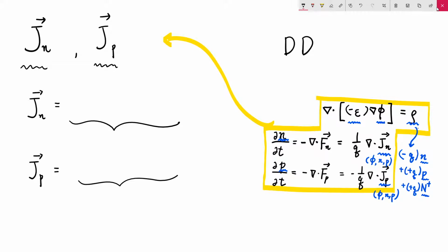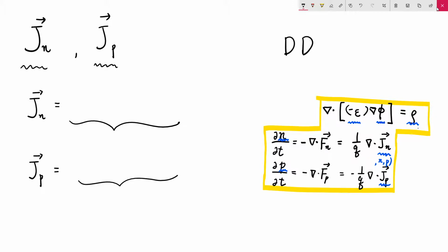Although it sounds confusing, when we just consider these three sets of equations, they are not related to the name drift diffusion. Where can you find the drift term? Where can you find the diffusion term? It is not found in this form. The physical mechanisms of drift and diffusion for transporting charge are hidden in the Jn and Jp terms. So now we go to Jn and Jp.